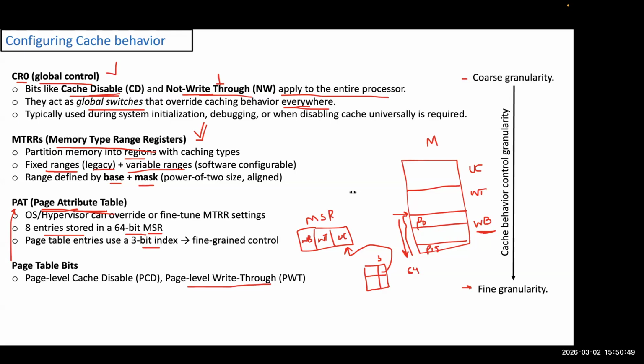If I send an update, I'm sure that update goes directly to the non-volatile memory without being stored temporarily in the cache, so I can avoid the situation where the power is lost and as a result my data is also lost. All the time I'm disabling the caching and I want the data to directly reach the non-volatile memory.